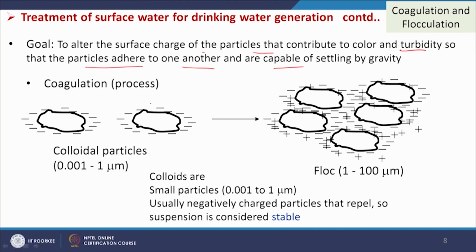So, very fine particles will not be able to do so in the water, but if we add some coagulants or flocculants, then charge neutralization can take place, and the particles will be able to come closer. If we make some slight agitation, then they will become closer and a bigger agglomerate will form, and that will be settled, and this is the mechanism for this.